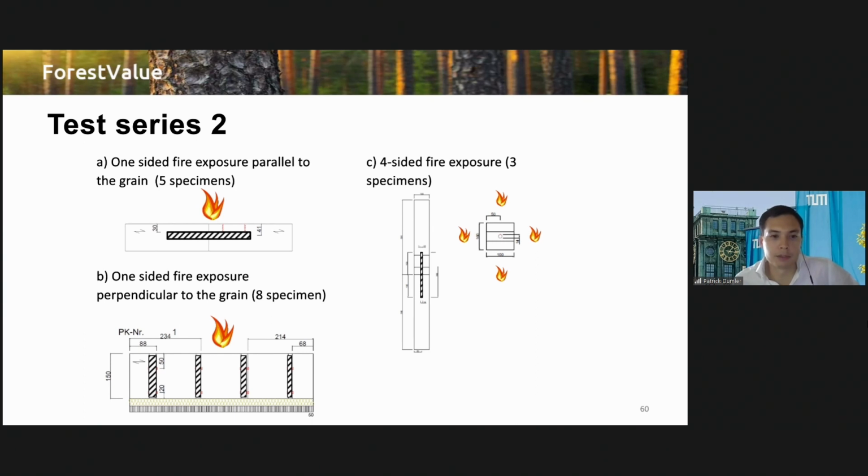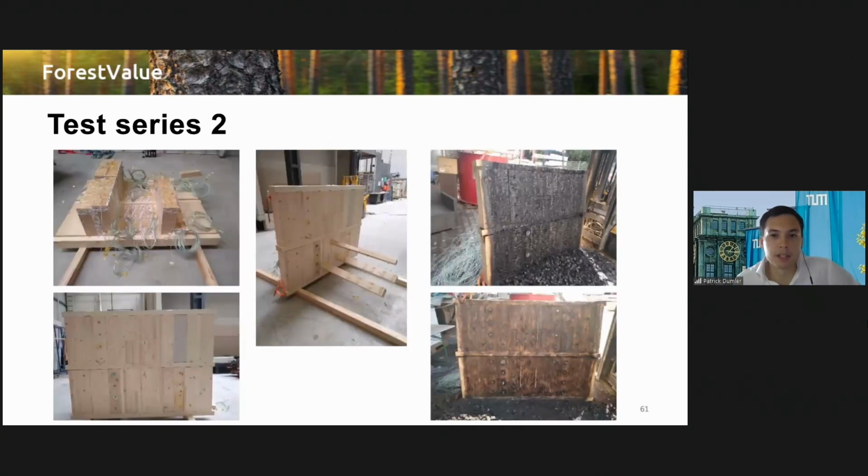different coverages of the rods, so they aren't exposed to the fire directly, like with gypsum plasterboards or different wooden plug thicknesses. And then there were thermocouples inside to measure the heat. And the test results were used to adapt the material parameters in the numerical simulations. So we could simulate the heat development inside different types of connections.